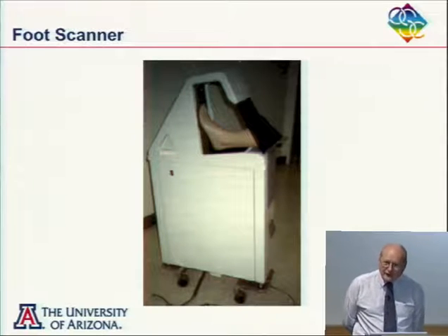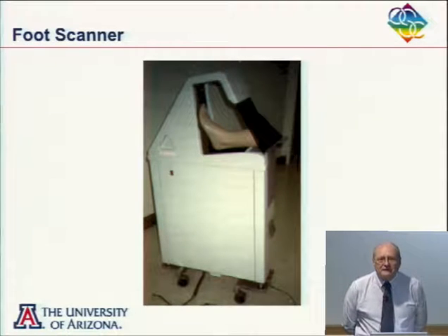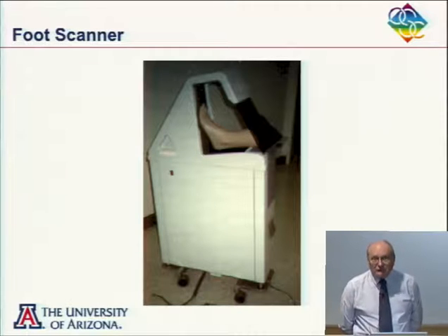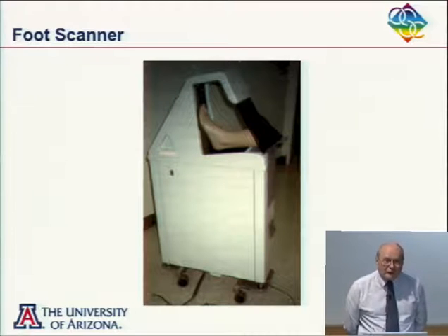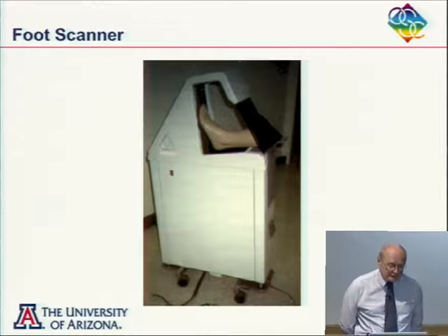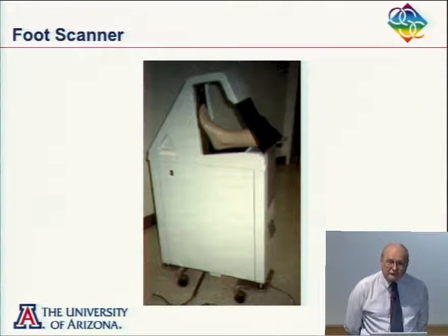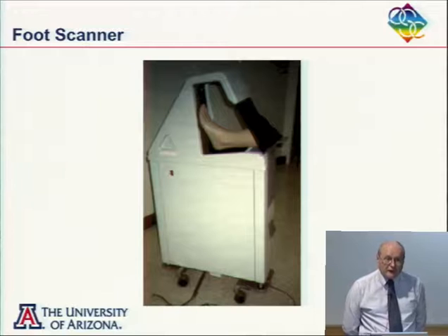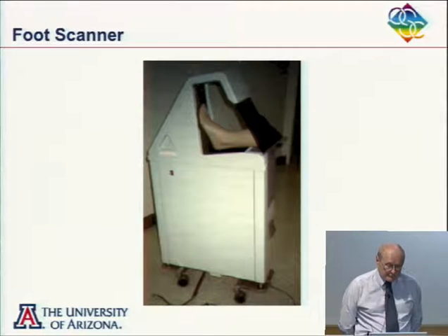Yeah, there are a lot of applications of this. Unfortunately, it's not for testing aspheres, but that technique might be used for the grinding phase. Right, you like to have a diffuse surface because you have to get light back to the camera, so it would work better in the grinding. In fact, I don't have the results here, but I've taken measurements of ground surfaces of a lens or a mirror. It works well, and it gives you the accuracy that you want. So it's pretty cool.